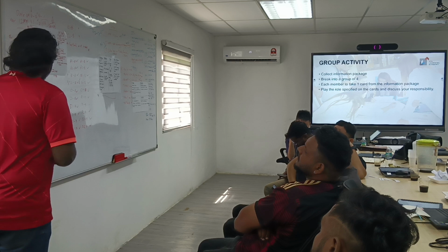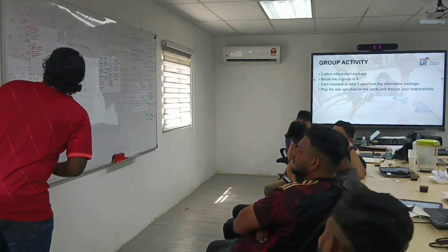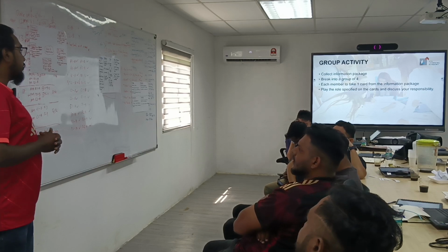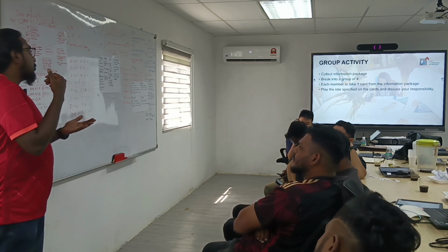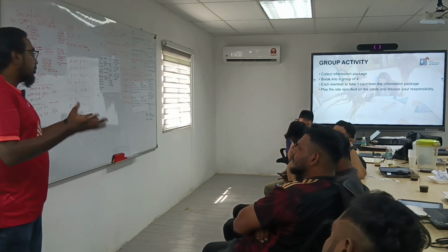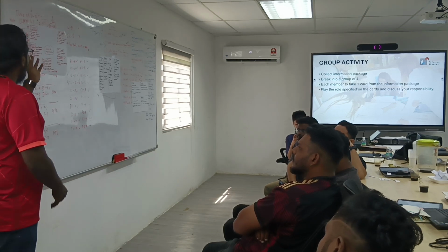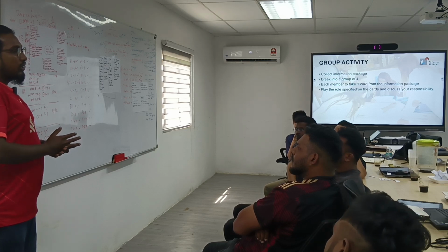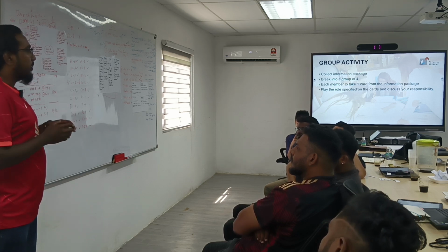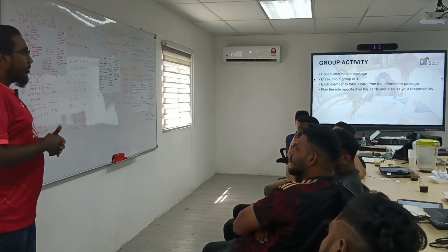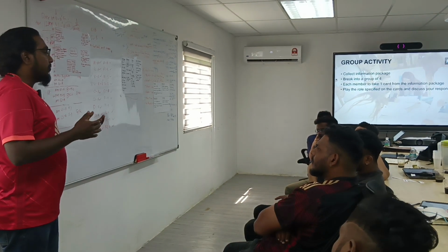And next is the consultant. So consultant, their work is to review design, they do, and then giving approval on the design. They will check on the design first, drawings mainly. If as you see, to do installation or to fix materials in a site, we need a drawing, and this drawing must be approved by someone. So that someone is the consultant. So that is when you see some progress are delayed because there is no shop drawing. So our main thing is our shop drawing. Once our shop drawing is approved, then only our subcon can proceed to do the installation. Without that, proceeding to do the installation is quite risky if it is not approved.